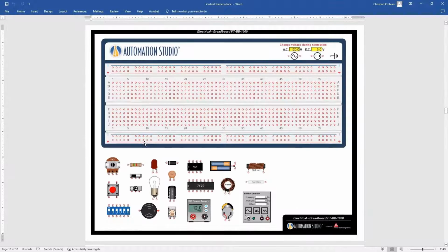We also have a breadboard where you can use the DC library to put components straight on the breadboard and make your connections. Okay, I know we have a new component in electrical. They created the op amps in the library, but because it was released right before the version was certified, we didn't have time to put chips like the 555 and the 74 series for the op amps. Okay, so this will come later on, but nothing stops you from putting an op amp on the breadboard or beside it and just running the wires to the breadboard to connect it.